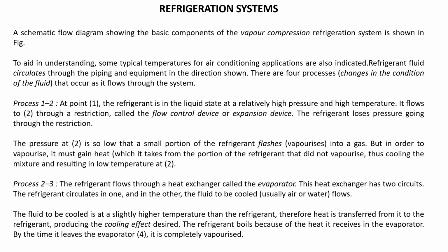So when it enters point 2, only a small portion of the refrigerant evaporates in the form of gas. Since this is an evaporation process, it must gain heat, which it takes from the portion of the refrigerant that does not evaporate.